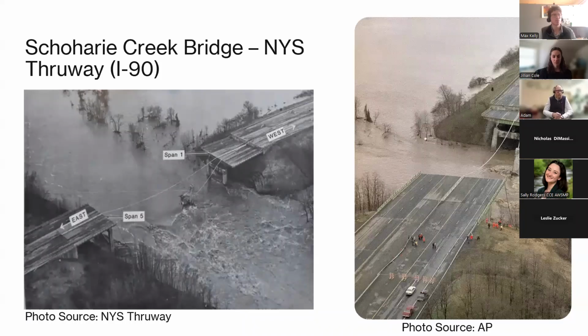It was a result of design decisions that didn't consider the potential for this bridge to scour. It was designed with reinforced spread footings, which were relatively shallow, and then those were just protected by a dry layer of riprap. So during these flood conditions, that riprap was removed, the footings undermined, and we saw 3 spans collapse into the Schoharie Creek.